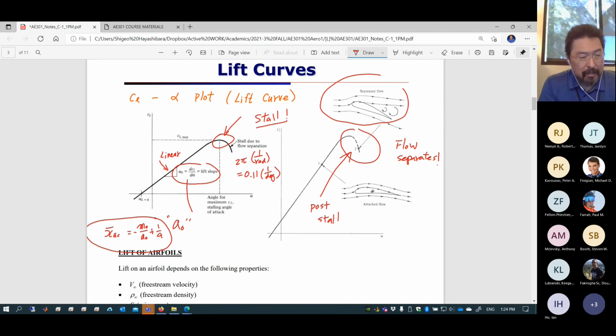But at the same time, you don't want to choose a very, very thick airfoil for high-speed airplanes, and vice versa, a very, very thin airfoil for an airplane which requires huge internal volume. So it's always a trade-off, but the design of the cross-section significantly changes the post-stall characteristics too. We're going to take a look at it, okay?